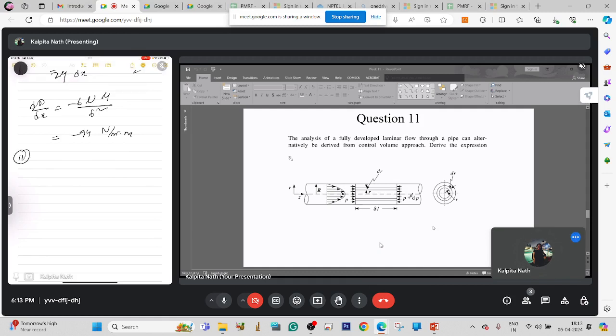So for this question, first of all, the fluid moves due to axial pressure gradient, right? Across the section the pressure can be regarded as constant. Due to the viscous friction, the individual layers act on each other, producing a shear stress which is proportional to del Vz del r. In order to establish the condition of equilibrium, we consider a fluid cylinder of length delta L and radius R. We'll be considering just a cylinder of length delta L and radius R.